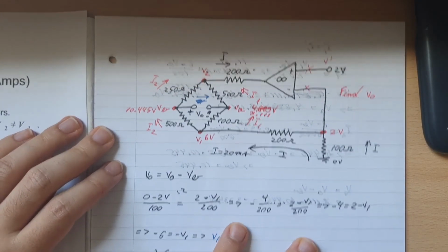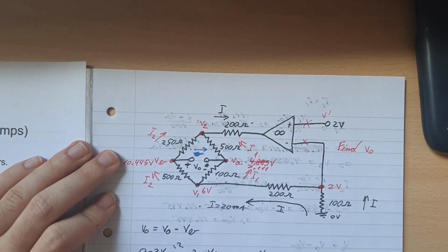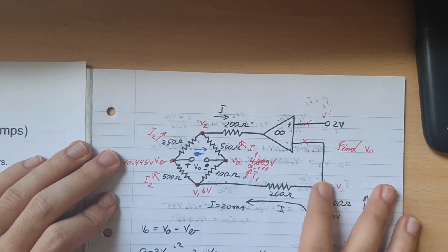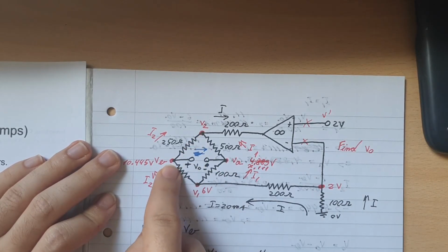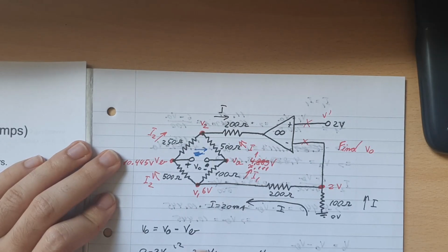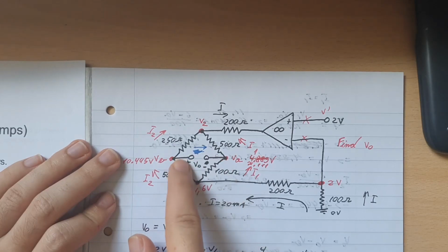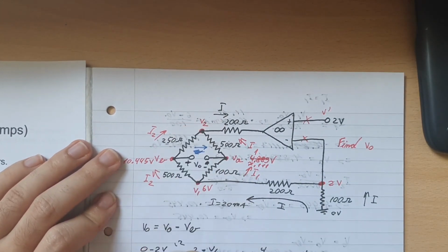But more importantly, remember to notate everything you can notate, because if you started without putting the 2 volts in here, without notating this one as V1, V2, and this one VA, VB, if you just saw the simple diagram with no notation on it, then it will get very confusing. We wouldn't really know if it's current going through here, through the V out, if it's only one current going this way, or what formulas we can apply inside of it.